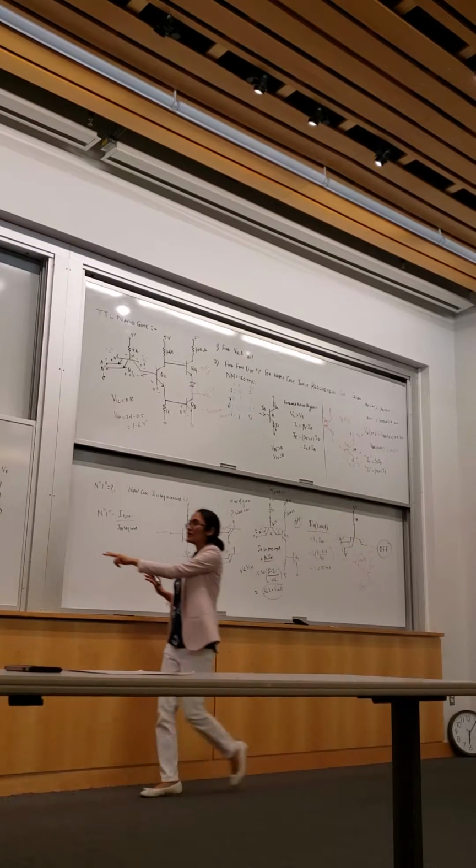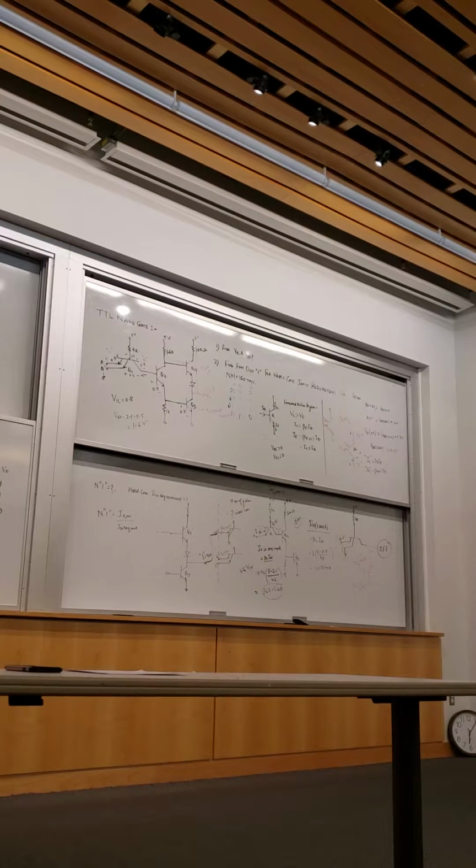And for the first case, it's easy, right? Because both are low, we have 2 diodes. Whatever current we have here is going to split into 2 branches, and you are interested in just one branch, right? You guys follow what I'm saying? So this is sitting at 0.7 volts. This is 5, whatever the resistance is. So for this case, your IIL would be 5 minus 0.7 divided by 4K times 1 over 2.